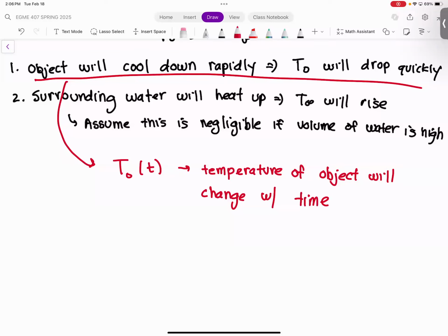And so that's exactly what we want to solve for in this situation. Under the lumped capacitance assumption, notice how this temperature is not a function of x, or a function of space. The only independent variable in that function is time. So this is quite different. Everything up to this point, we've been solving for temperature differences in space. For the first time, we're actually going to solve it in time. Because we can't solve partial differential equations, time is going to be the only variable that we have. And the only way that assumption works is if we assume that the object is at the same temperature throughout the entire object. Any questions on this so far?